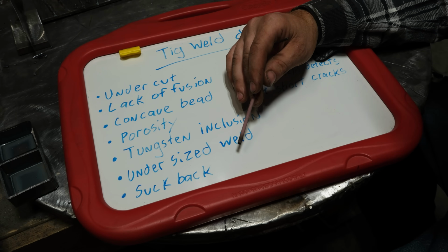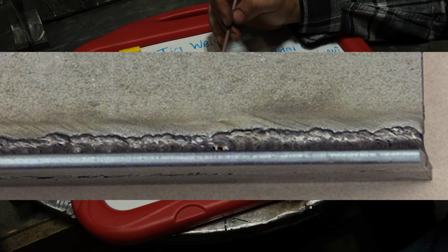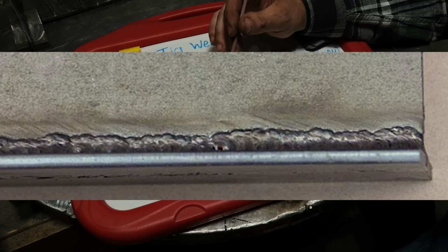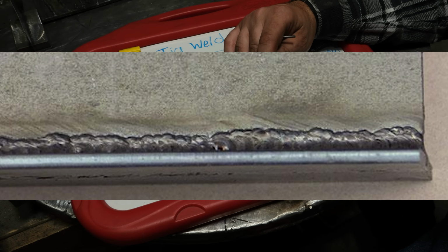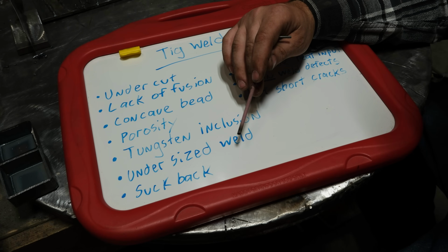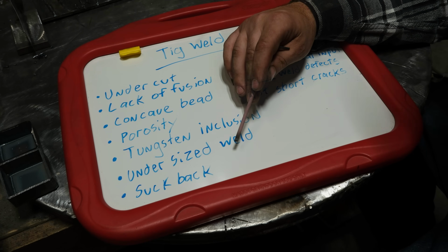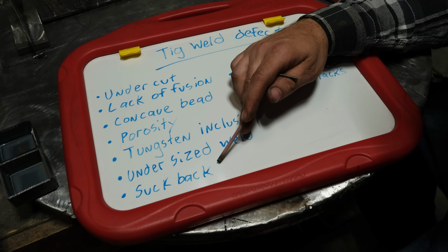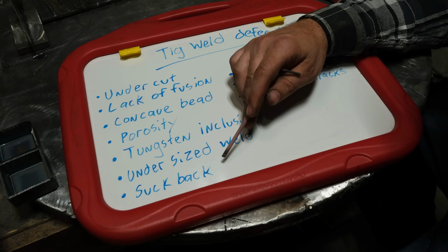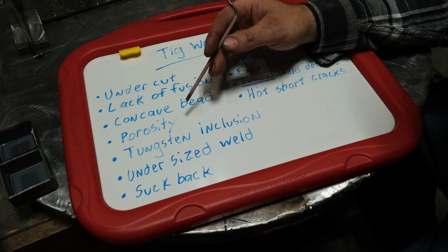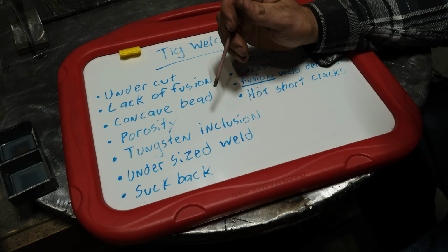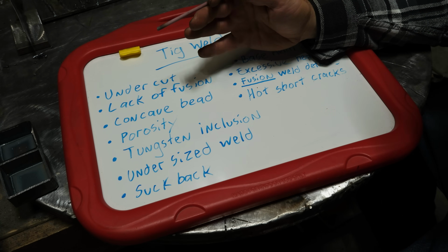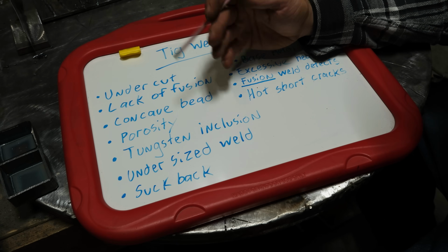This is undesirable for the same reason why undercutting is undesirable, and that is you will have a very thin line where the base material is more or less necked down, and it will propagate a crack or just be weak simply because it's thin at that point. Probably the most relatable situation that this could cause you a nightmare of a bad day would be if you're building headers for your race car, your truck or something, and you're welding the tube to the flange that bolts to the exhaust manifold part of the cylinder head.